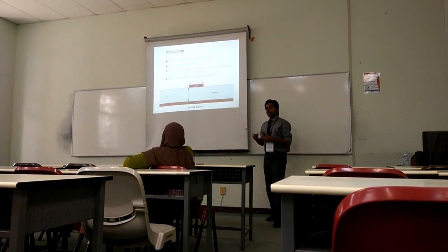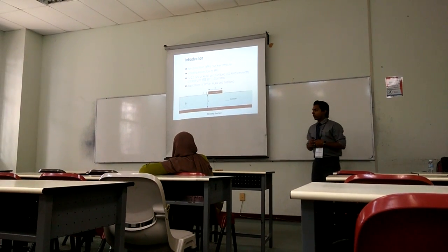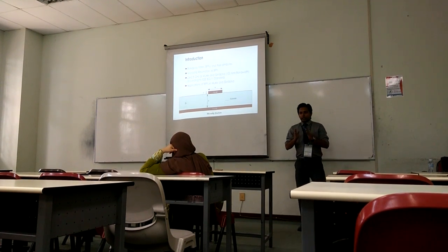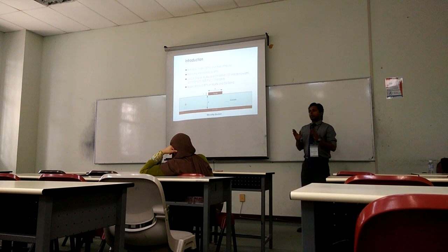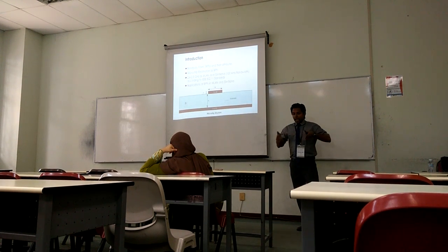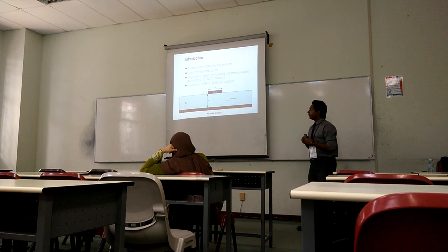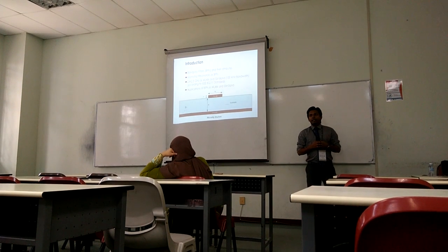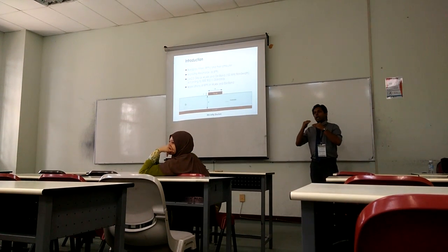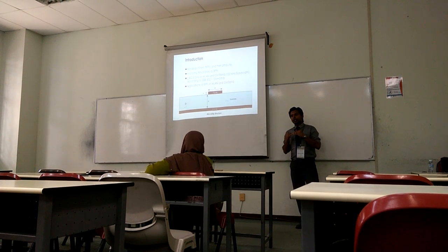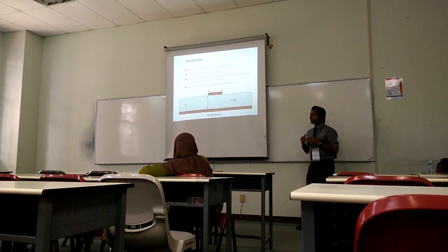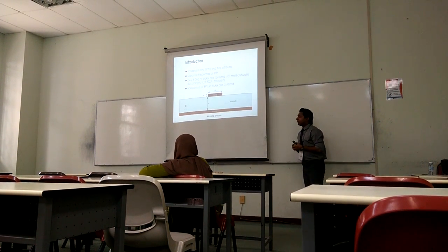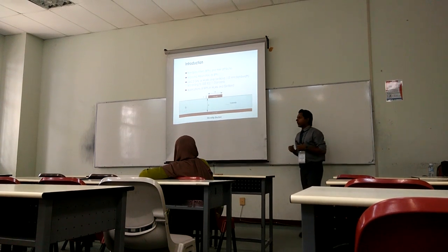So for bandpass filter, there are some very common attributes you may already have known about. The first thing is the bandwidth that we already mentioned. What's the bandwidth? It depends on various things, but it determines how you are choosing a specific band. So the bandwidth is the most important for a bandpass filter. Also, the insertion loss. It determines how much strength of signal you're losing. If the insertion loss is high, then you will lose too much signal strength. So it's another important point of the bandpass filter. Another is the reflection coefficient, that is one parameter.